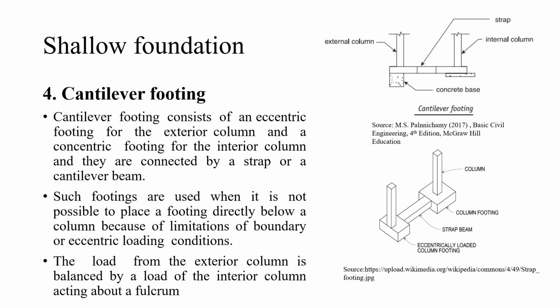The next one is cantilever footing. These may look the same, but the cantilever footing is very much different from a combined footing. How? Say for example, there is a plot in which you are doing a construction. You are not giving any offset. For the sake of wanting a very big structure, you are extending your construction until the extreme end of the plot.